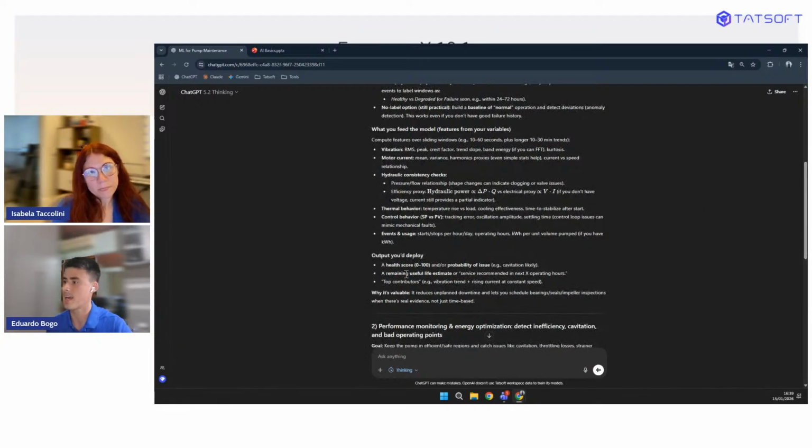The top contributors is very cool, because if you have like 15 process variables, you can plot in a trend visualization or bar graphs which process variable has more impact on what's happening. Let's say that it could be overheating. In this case, probably the temperature would be the biggest bar, or maybe the speed.